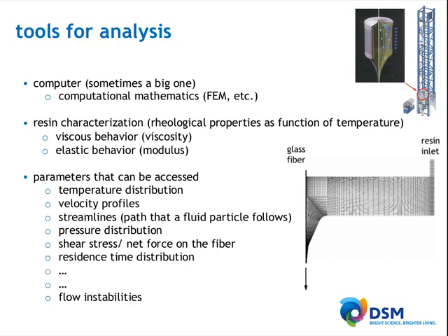Now, if you look at these finite element methods, one of the key ingredients there is a finite element mesh or a finite element grid, sometimes it's called. And what I'll show you is some results of a coating die, typically what you see on the right top, the small insert there. But we don't do this in a three-dimensional fashion. We consider only one cross-section of this coating die, as you see in the image below, and then assume that over the circumference of this coating die, everything remains equal. And in practice, that is a very normal assumption, which holds to be true.